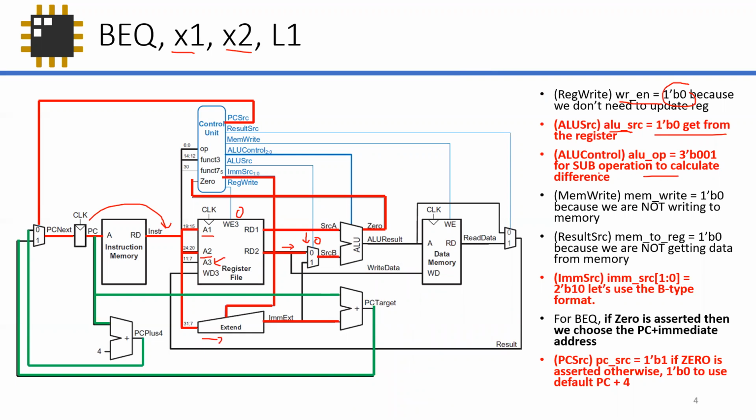And then ALU operation. So when we compare operations, we compare them by setting the ALU operation to subtraction. All right. And then you know if it's equal or not if all the bits of the result are 0. Say for example, source A is, I don't know, 10 in hex. So you could write it with 0000 something up to A, the 32 bits. And then source B is also 00 dot dot dot A. If you subtract them both, you will eventually get a result that is 0.